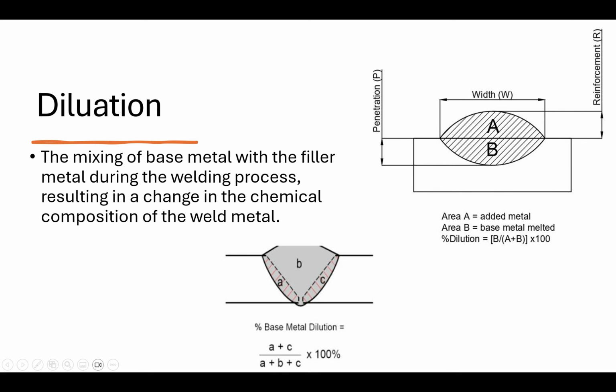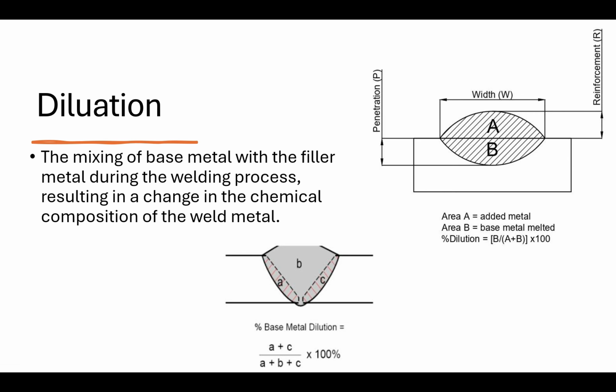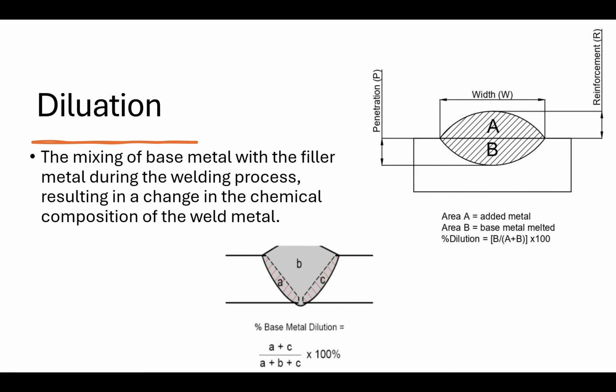And what is most important, when the electrode is melting the base metal, say this side is carbon steel. So carbon steel has a high percentage of carbon, for example 0.3. And now the electrode has a much lower percentage of carbon, so when it dilutes, you are going to get enrichment of carbon in the weld deposit here. And stainless steel has a maximum of 0.08%. So from the carbon steel side, carbon is coming into the weld pool. And here again, SS316 will not contribute much because it has a low percentage of carbon anyway. So this deposit will have different chemistry than the original that comes from the electrode as well as the individual base metals.